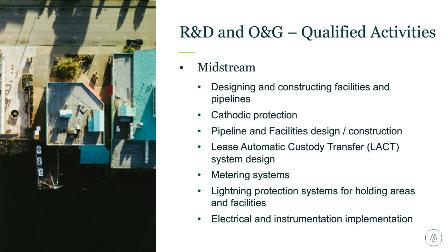So there's a lot of different systems that go into a facility design, where you have supervisory control and data acquisition, or SCADA systems. And you also have pump stations, which in themselves are pretty much an R&D project, because they have their own design, their own infrastructure, their own piping, sewer systems, etc. Next, we have LACT systems, which is the lease automatic custody transfer systems. And those themselves can be very complicated from an instrumentation and mechanical standpoint, depending how big they are, what's the nature of the fluid actually moving through them.